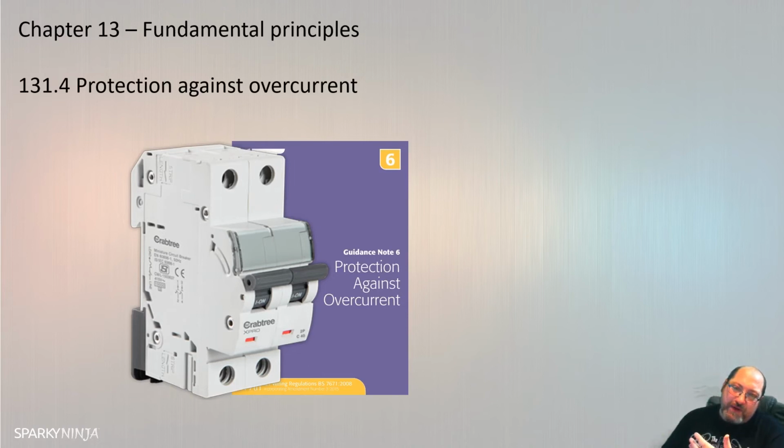What we need to consider, however, is when we achieve these low impedances to achieve these high currents for short duration, can the live conductors' operating limiting temperature, their insulation, tolerate this increase in current for this duration? And then later on in chapter 54, we'll also be saying, if the protective conductor is being used in an earth fault, can that protective conductor actually carry that current for the required duration as well? So we'll look at the thermal